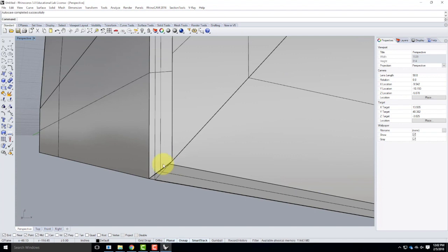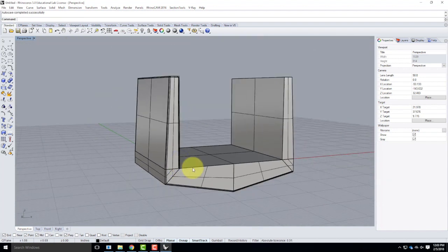And so I like to bring up 2 points. Number one, if I was rendering this, imagine this had a texture on it, and I was rendering it from this far away. Could you tell that it had a little gap? Nope, not at all. So if your desired end output is just that you want to do a rendering, spending your time correcting that is not worth it, because you're never going to be able to tell in the rendering. However, if you were going to 3D print this object for some reason, that little hole would cause it not to 3D print.